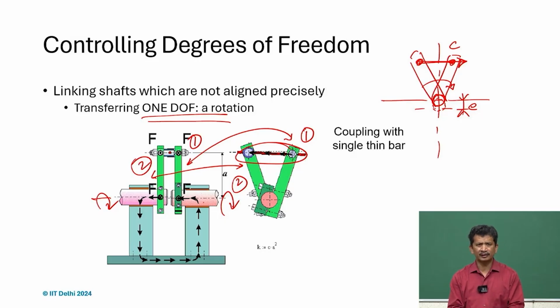Later we can replace it with the wire flexures, and if you really want to test whether this kind of constraint can work, we can put it in an antagonistic way, and we can simply put a kind of thread or flexible cable also, because in that case one of them will always be in tension, and it will give that required rotational constraint.